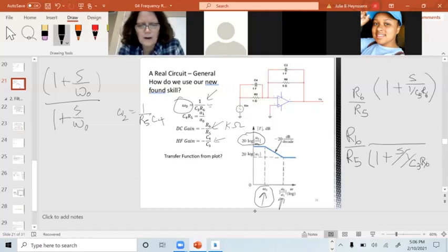And I just copied the value from this, and this was labeled from this. A0 over A1 is this omega 2, what I called omega 2. That is a place where suddenly the gain must be rising because something's canceling out that minus 20, and it must be a plus 20 dB per decade. So that's putting a zero up here at 1 plus S over my omega 2, which was 1 over, I'm sorry about this, I'm just excited, R5 C4.